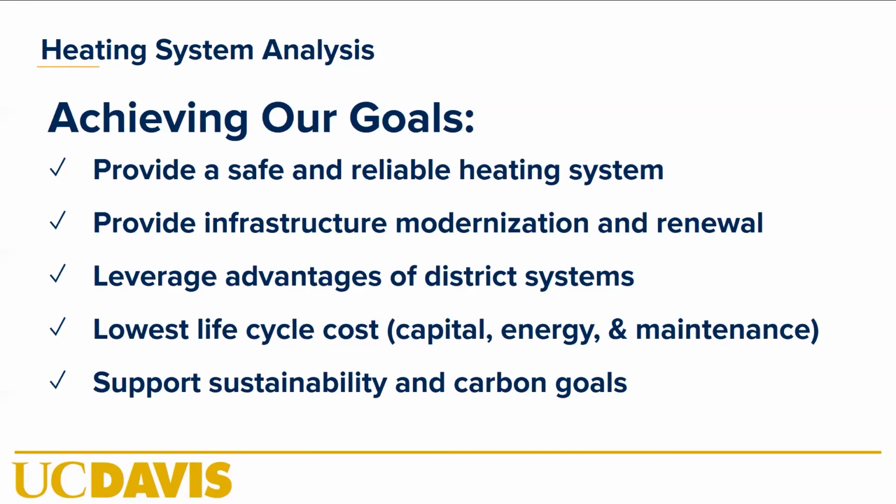And so unless you have a smaller system where you can do some kind of seasonal storage, that didn't work as well for us, mostly because we already have a chilled water system. If we didn't have our district cooling system to do heat recovery, solar thermal would have been the best option. In fact, we have another district system at our primate center on the west of campus, and we are doing solar thermal there because we didn't have as much cooling in the winter, and so there wasn't that heat recovery opportunity. So solar thermal is very much a good option with the right kind of fit.